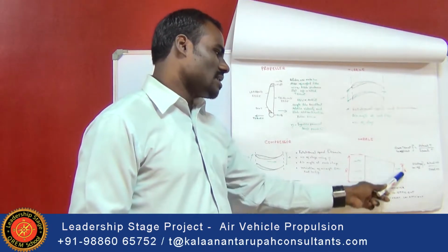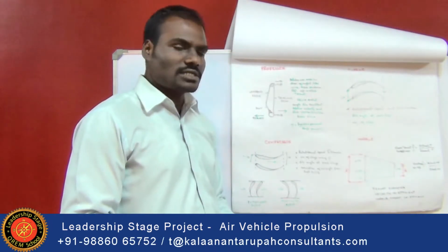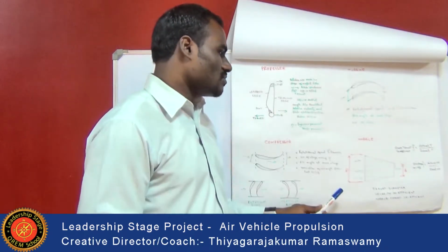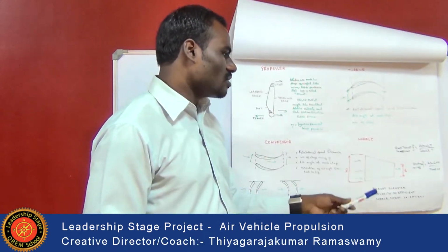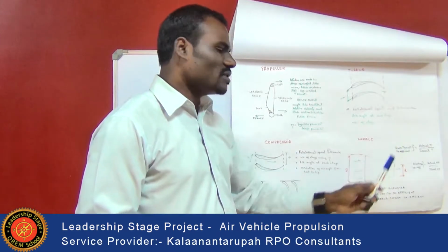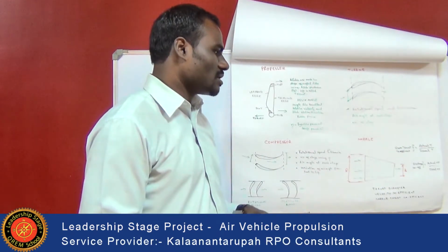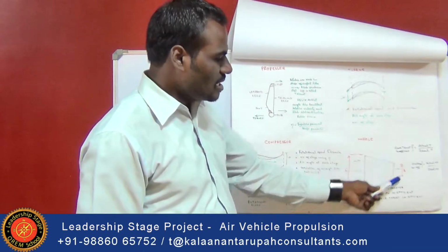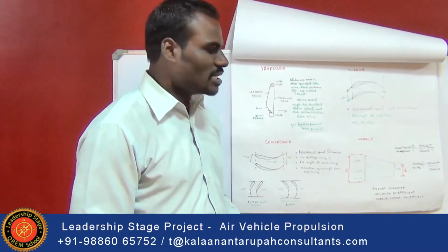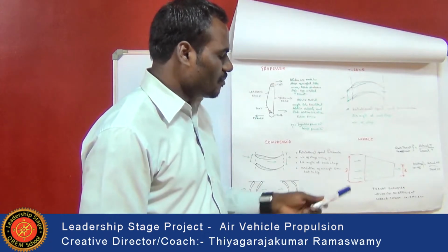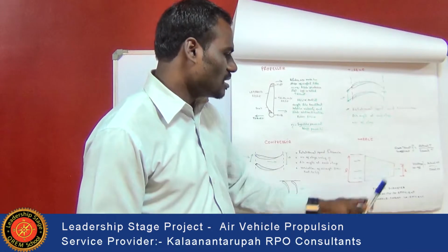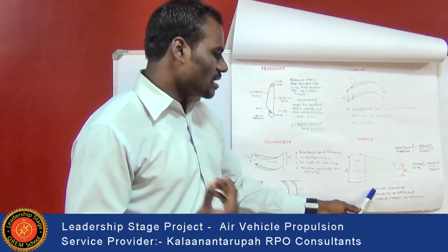Many considerations have to be made with respect to the nozzle structure, such as the material being used. Other things to consider in designing the nozzle are the gross thrust coefficient, which is the actual thrust with respect to the ideal thrust, and the discharge coefficient, which is the actual mass flow rate with respect to the ideal mass flow rate, and the throat diameter.